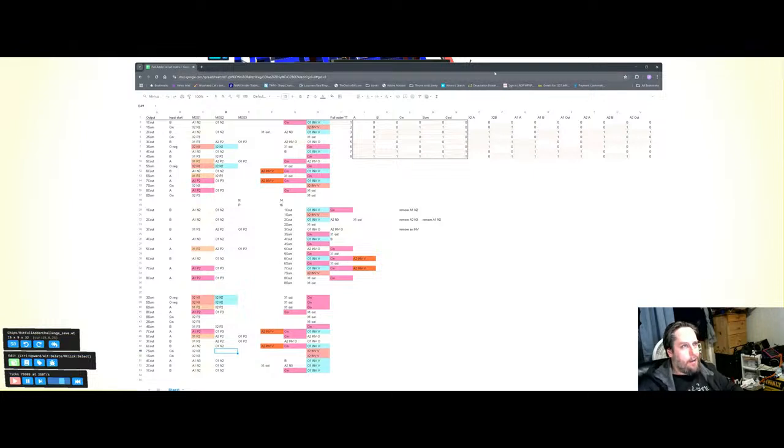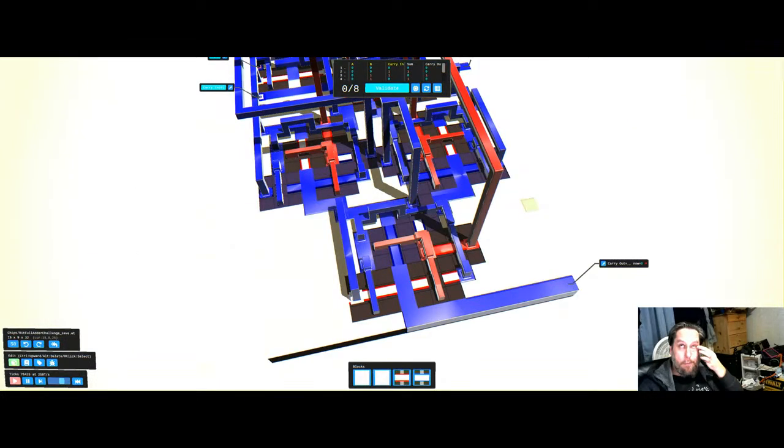In my fiber to the home designs, I typically would work it backwards actually. So a quick example of that is your blue tube is your primary tube, and I actually would make that the end of the line tube. So I would want it straight spliced all the way till the end of a line in some neighborhood or wherever it's going.